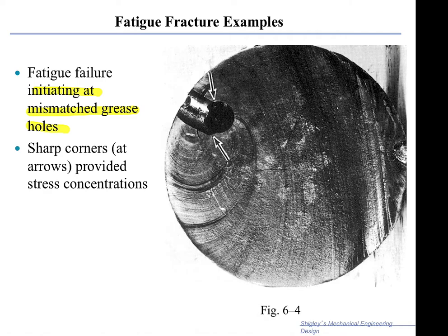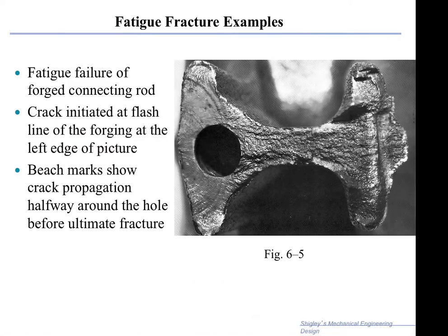And in this case, the fatigue crack initiation is right there, and then you can see as you have propagation of the crack, it just kind of moves around and fills in, so the crack is continuously growing until you get no additional space for the material to carry the rest of the load, and then you get eventual failure either by brittle or by ductile mode, depending on the type of material we have.